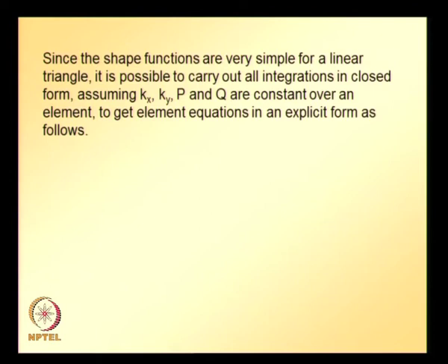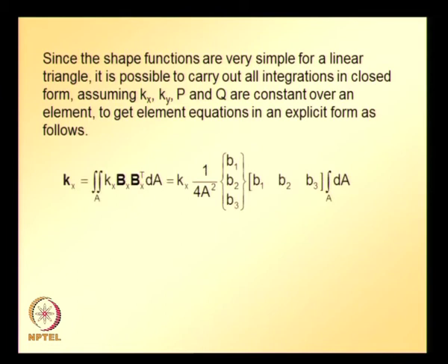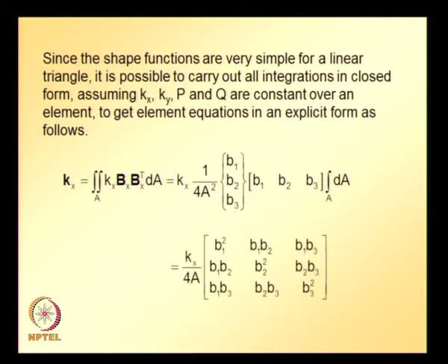For the linear 3 node triangle element, since the shape functions are very simple, it is possible to carry out all integrations in closed form, assuming kx, ky, p, q are constant over the element, to get element equations in explicit form. So, for the 3 node triangle element, kx turns out to be this, after multiplication of the 2 matrices and vectors. Similarly, ky